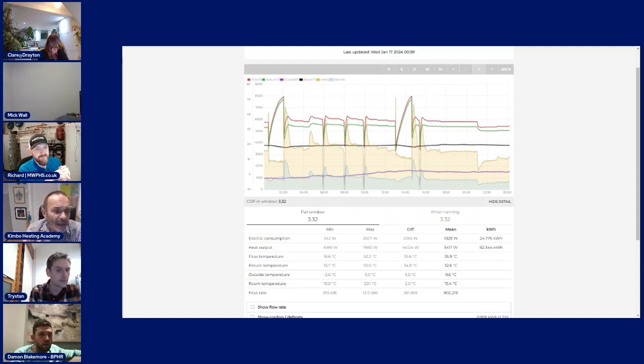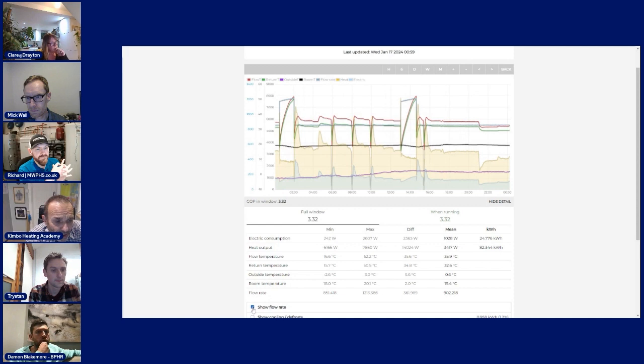Yeah, and Kimbo, good as you have as well, a question? Yeah, mine was regarding the flow rate. Something you noticed in the data you were looking at led you to think there's a restriction of flow somewhere, and presumably as a result you took out these IMI ones and put in the flushing valves and noticed an immediate difference. Was that because the original flow rates were incorrect, or do you think the flow rates it said it was doing, it wasn't doing?